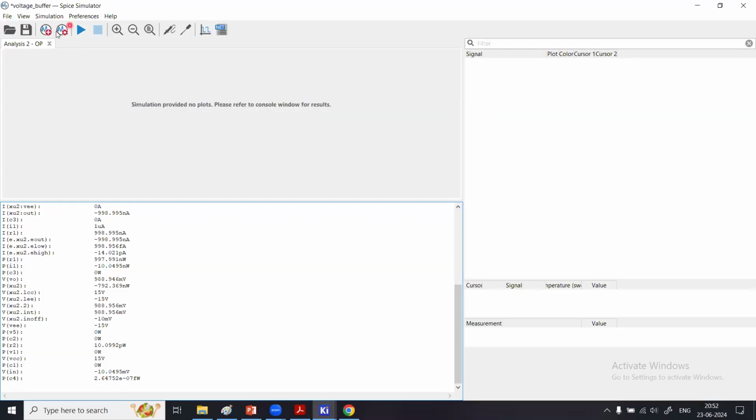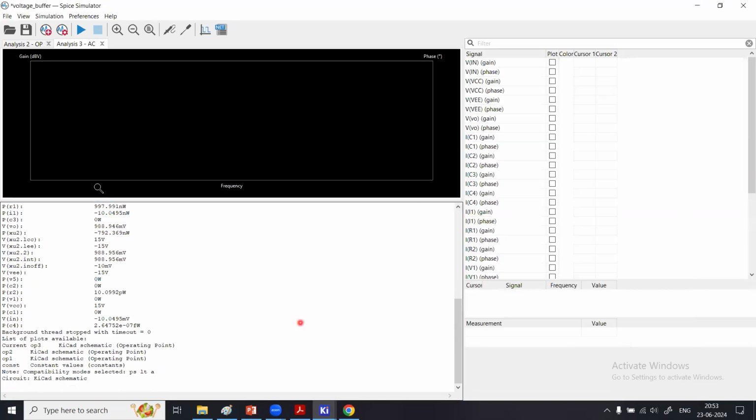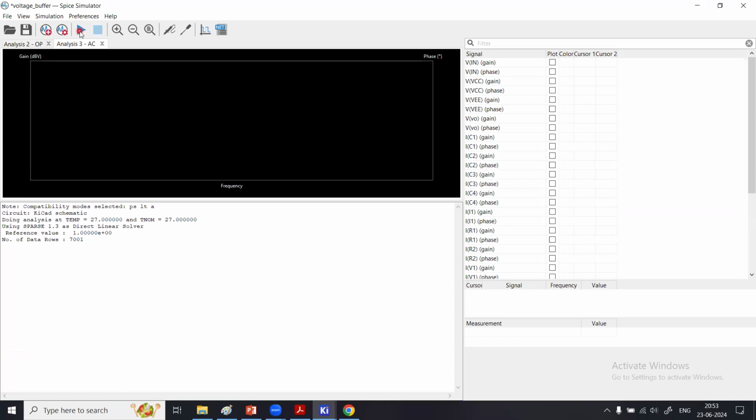Let me just check here, click the new analysis, go for small signal AC analysis, click, let's say 1000 points, start frequency 1 hertz, stop frequency, let's say 10 megahertz. Click OK. Once that is done, click simulation.